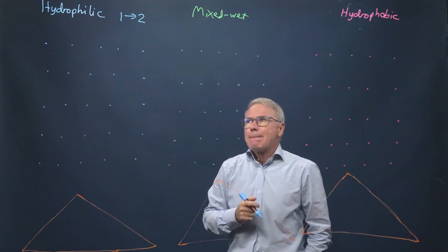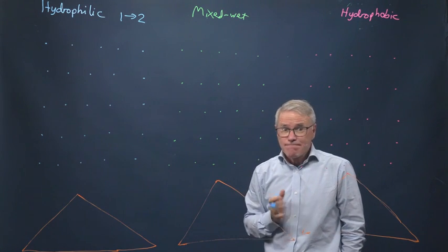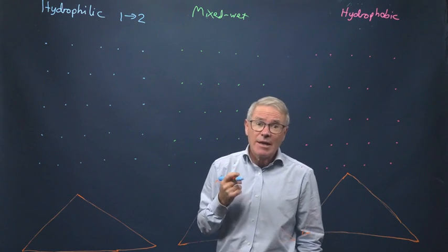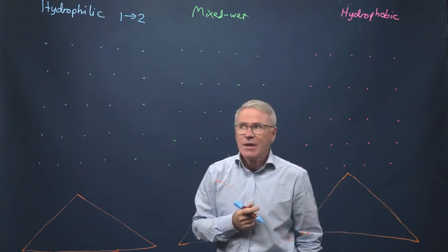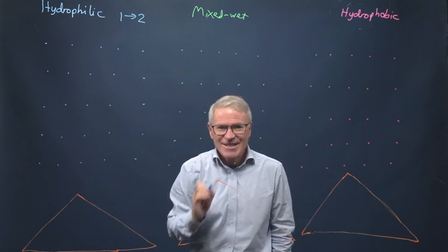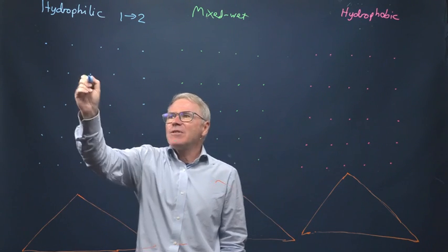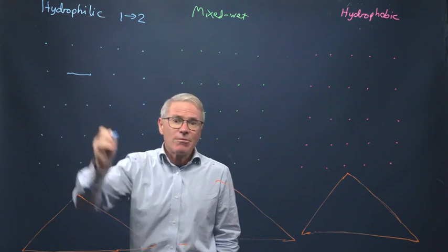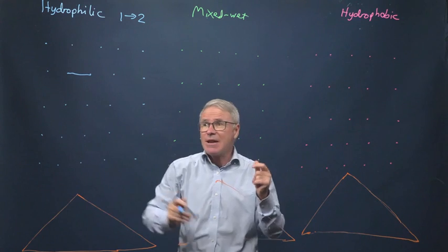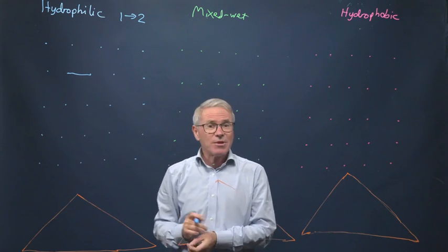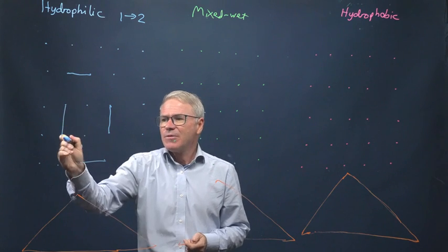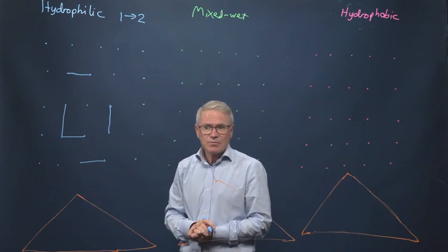So let's look at the hydrophilic medium first. We've already discussed this. This is a percolation type displacement. So when the wetting phase, which I'm going to indicate in this case in blue, moves in, it first of all just fills the narrowest regions of the pore space. Okay? And that's by snap-off. So just by random, imagine that's the narrowest throat. That's what it's going to fill. Then it's going to fill this one, and this one, and this one, then it's going to fill this one.